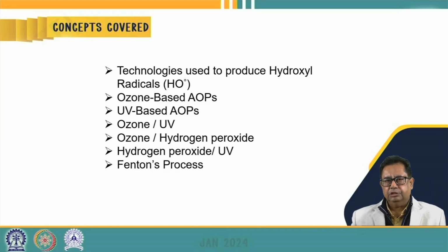So, it does not discriminate what type of organic compounds are present, and whatever can be oxidized, whether it is organic or inorganic in nature, can be oxidized by the dot OH radicals. So, they are highly reactive species which can lead to the oxidation of any recalcitrant compound also present in the wastewater systems. So these dot OH radicals can be produced by a variety of techniques.